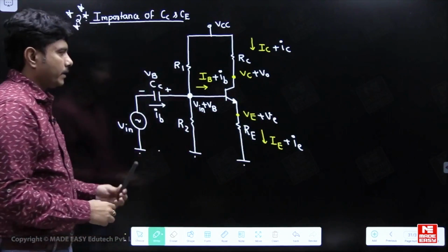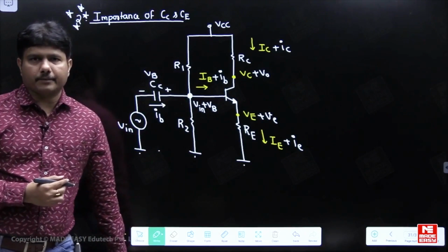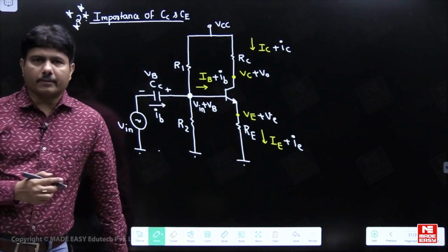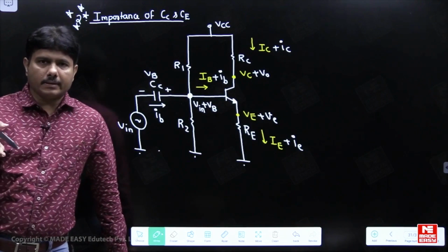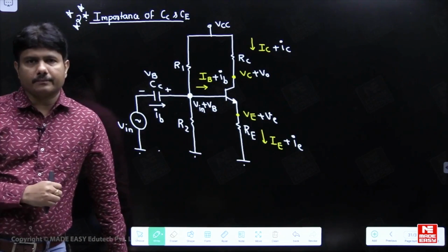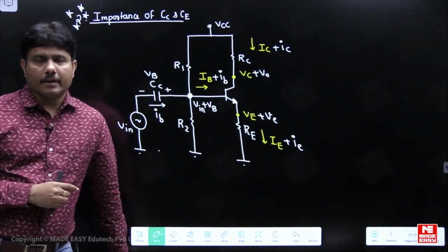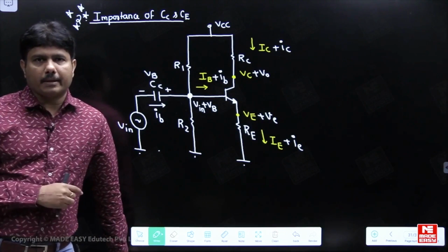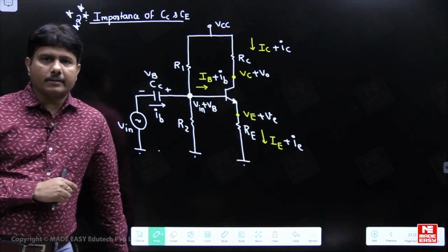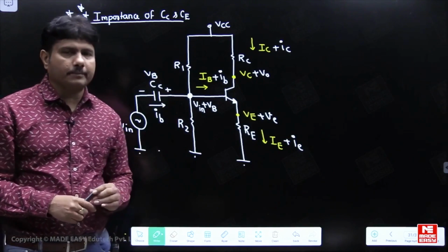Like this you are going to get two voltages and two currents in the diagram. In your amplifier circuit now, two voltages, two currents will be there. One is AC current, one is DC current, one is AC voltage, one is DC voltage. That means our interest is AC should add with the DC. Therefore, the currents also will get added, they will get amplified by beta times. You will enjoy the amplification for AC signal also. So this is the concept of how we applied it in the subject.